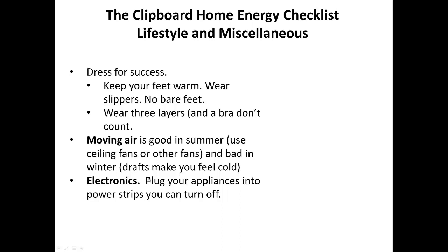For electronics, you want to plug your appliances ideally into power strips and then turn off the power strip. All of our little gadgets and doodads have little transformers, and even when they're not in use, if you put your hand on the transformer for your cell phone charger, it's warm. Well, if it's warm, that means it's costing you energy. It's pulling electrical energy into that transformer even when it's not being used. Some studies have shown that up to 11% of your losses are caused by these, what they call phantom losses.